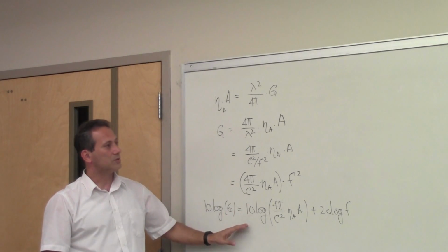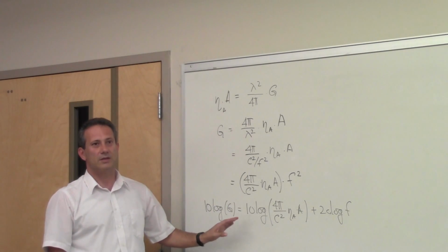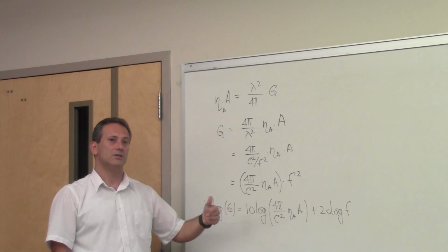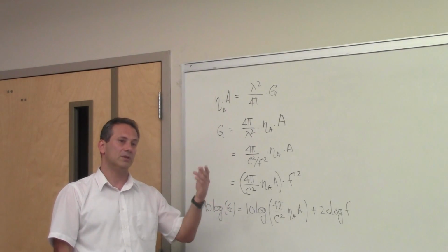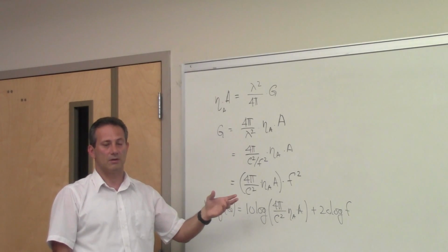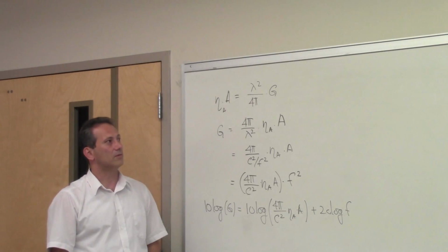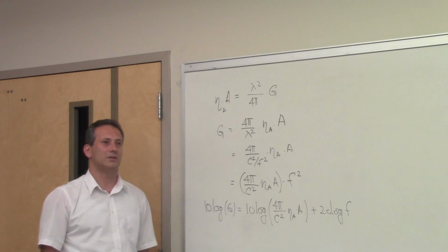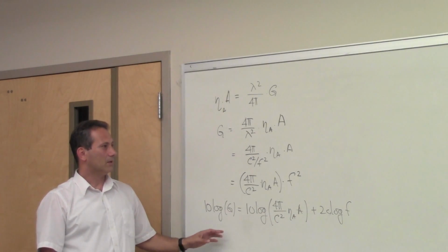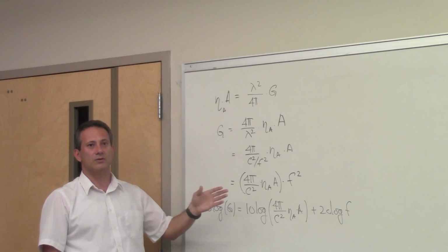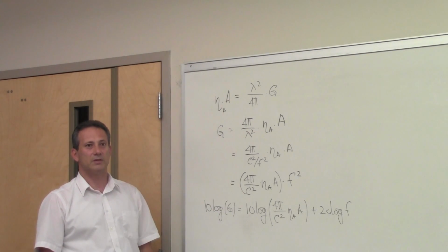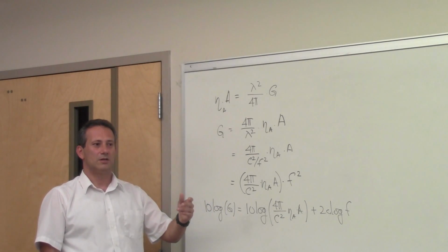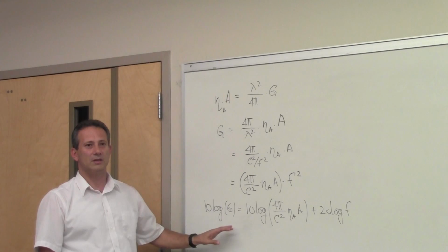Now, what you don't see from either one of those is that there are additional losses beyond those of free space, and these are the losses associated primarily with rain and all the other impairments that you suffer along the way that unfortunately increase with frequency. So there are multiple things in play. The thorough analysis of them will take us the good part of the semester, but typically people will say, oh, when you move higher in frequency, it is always more difficult to communicate. It might not be the case.